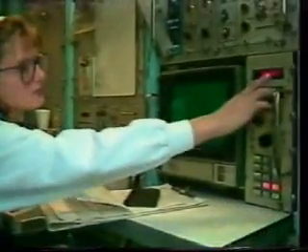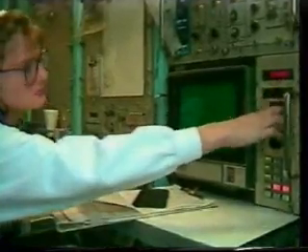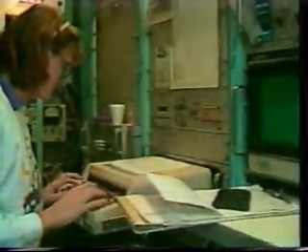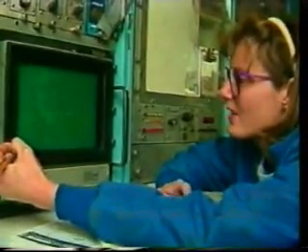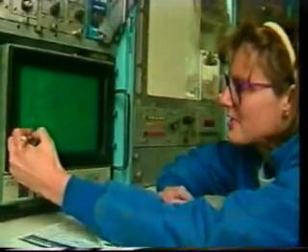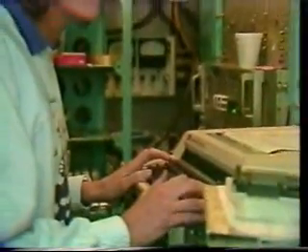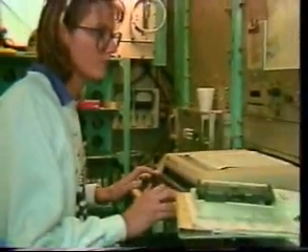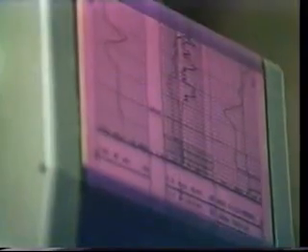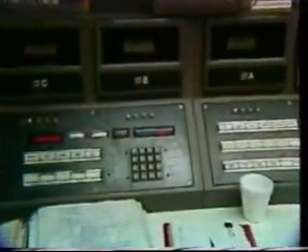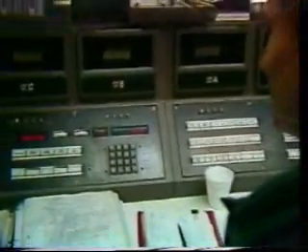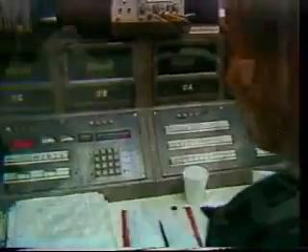For the on-depth check, the logging engineer verifies that proper displacement to one common depth point is valid. This is done by comparing all curves at lithology breaks to determine that they show lithology changes at the same depth. If not, the logging engineer makes any necessary adjustments so that on-depth plotting occurs. After logging the repeat section, the tool is lowered to bottom, and the repeat section log is examined. Now a final depth check is made, and with the repeat section in hand, the logging engineer gives the go-ahead for the main survey to begin.